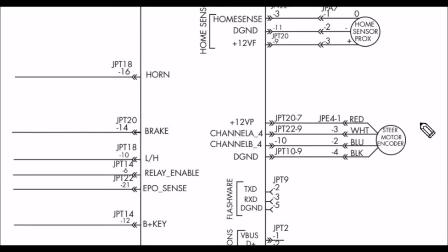Okay, let's do a brief explanation on why we always see a 5 volt even though we took out the connector for the encoder bearing. So we were back probing right here towards the computer, which is the white and the blue.